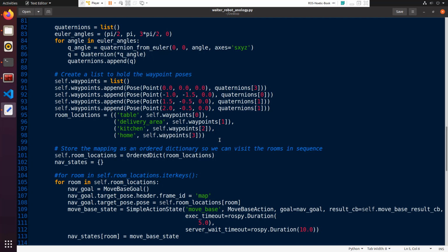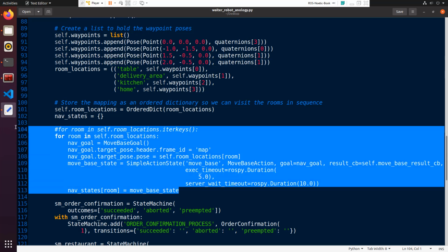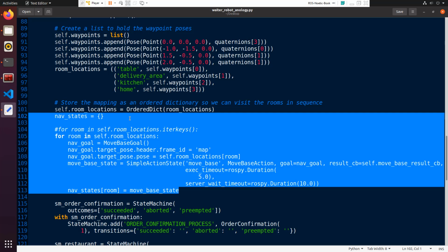Like we have seen, from RViz we can command the robot to go to one position using the 2D navigation button. The same thing we can do from a program. We can give x, y, theta values from the program and the robot will move. That is what we are seeing in this example. So you can integrate the navigation stack client, SMACH and rospy in a single node. It is possible.